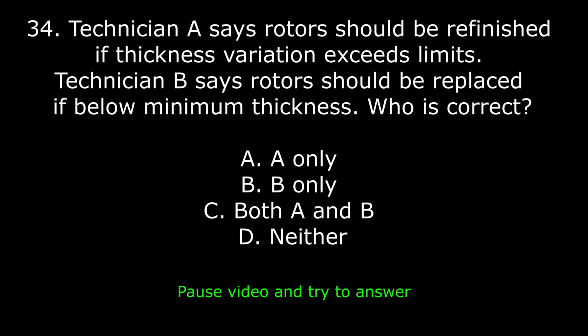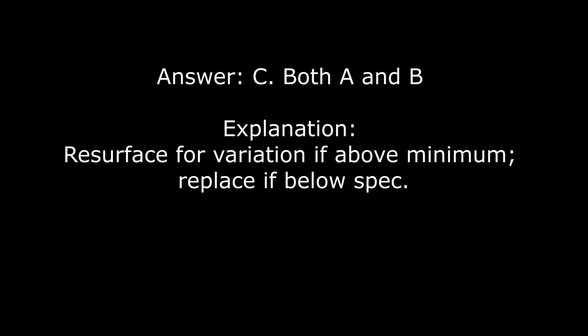34. Technician A says rotors should be refinished if thickness variation exceeds limits. Technician B says rotors should be replaced if below minimum thickness. Who is correct? A. A only. B. B only. C. Both A and B. D. Neither. Answer: C. Both A and B. Explanation: resurface for variation if above minimum, replace if below spec.